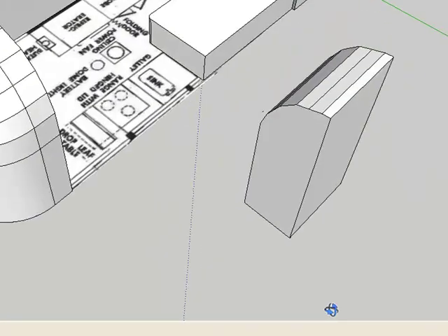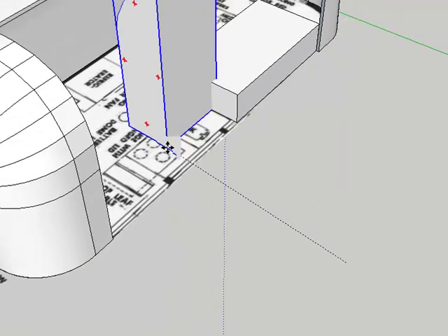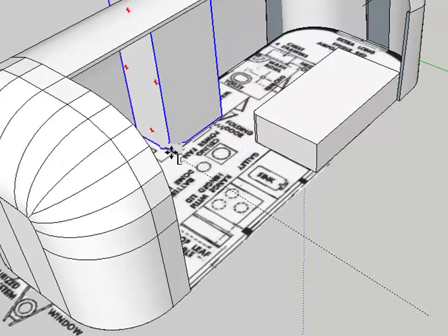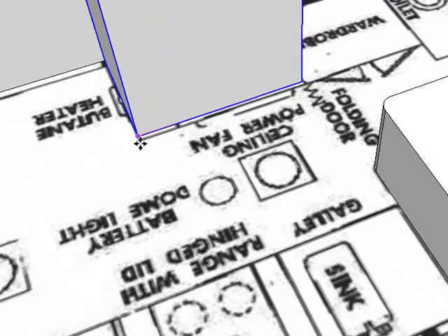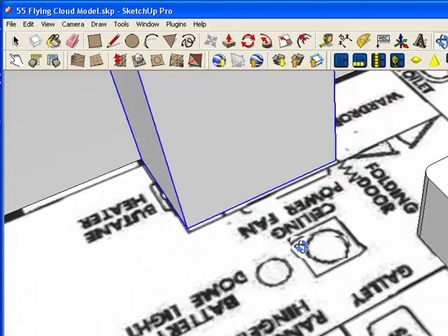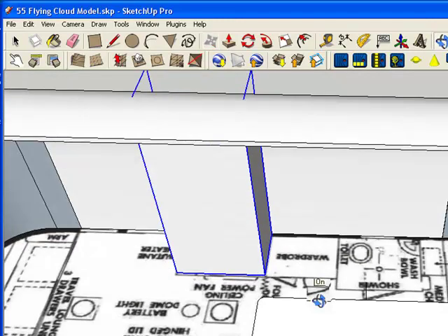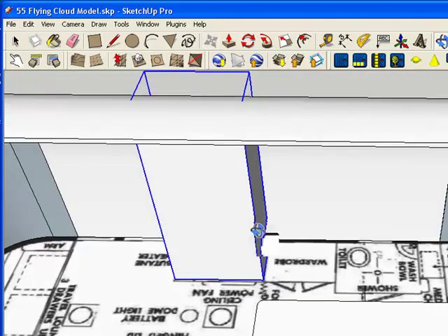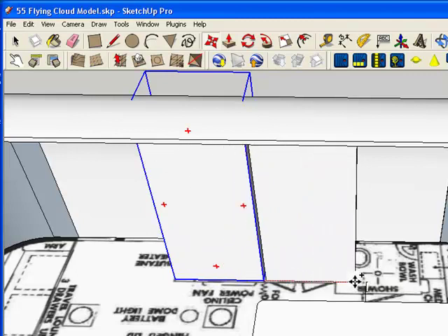for the refrigerator. And what I can do then is highlight it as a component, slide it back into place. Now, the other neat advantage is, there is a wardrobe closet right next to here, which is essentially the same shape, but it's just a little shorter. So if I use M for my move tool, which I have on, click on this cabinet, hit the Control key to duplicate, okay, bring this cabinet over.